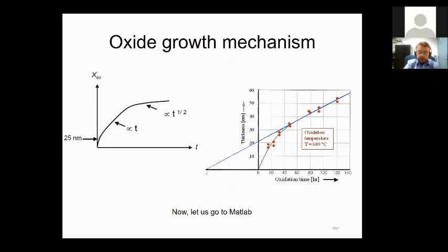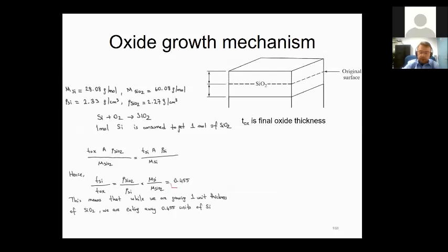We'll examine these things, the growth rates. So I'm skipping that shortly, but again, emphasizing this in this very simple examination. Let's say that we originally had the silicon wafer level to be like this at this point. And then we totally grow an oxide of T oxide, that much, okay? The level, since we are consuming the silicon, will drop. The new silicon wafer level will be much lower. So let's call this the consumed silicon, T silicon, that portion.